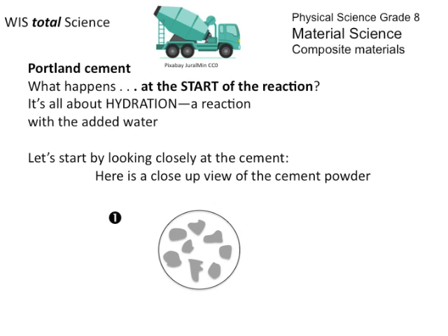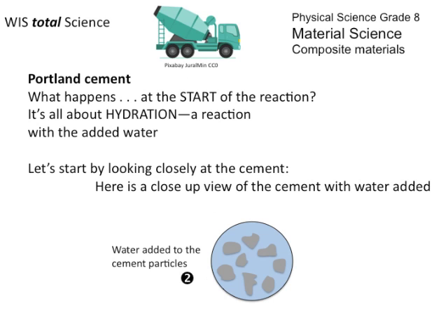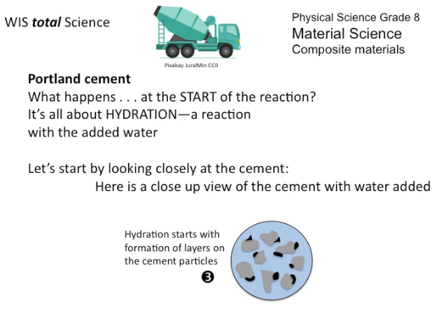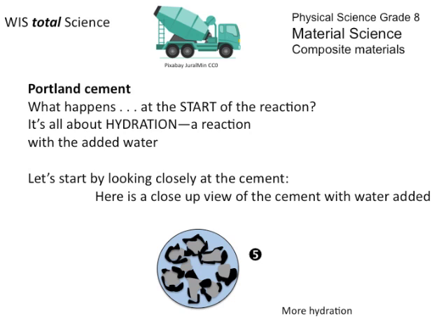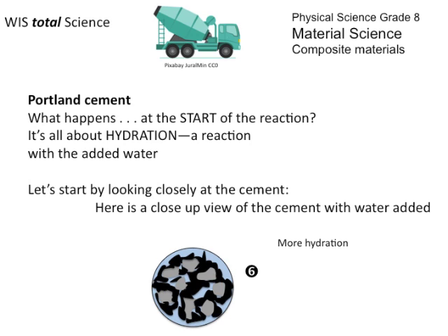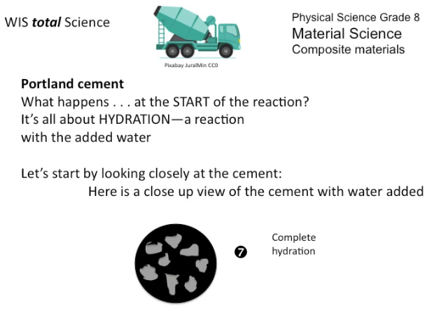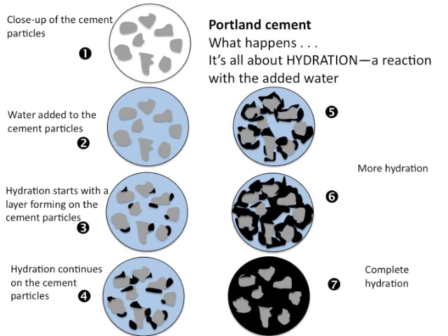And here's a close-up looking at the cement powder, adding water, and slowly you're going to form layers of water around the cement particles, and as it becomes hydrated, the particles sort of join together, and you mix in stones and it sets really, really solidly.